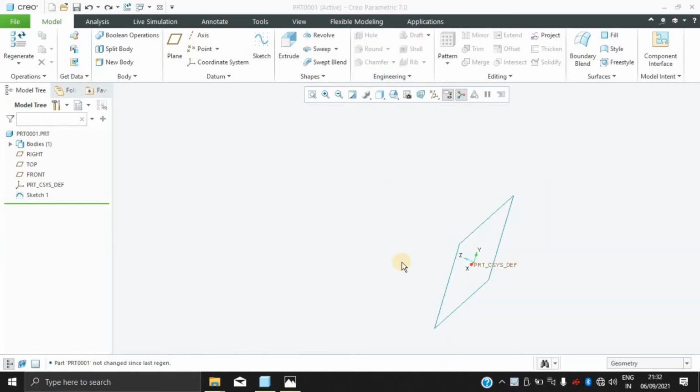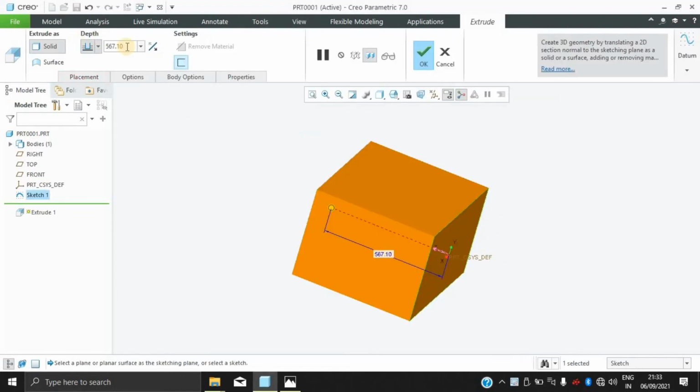Alright, so now we'll study about assembly in Creo, how to create components and how to assemble them in Creo. So first of all, I'll create two bodies, basically a plate and a cylinder. A plate with a hole, and that cylinder will be inserted in that hole itself. So okay, we'll first of all create a plate of diameter maybe 50.